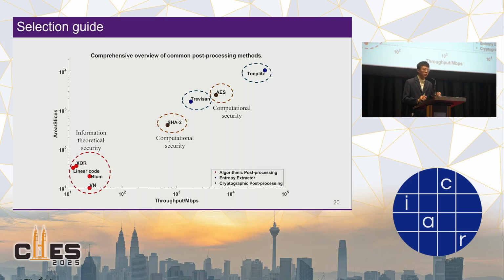You can use different single-bit extractors and different weak designs according to your specific demands. As for my configuration, the input density demand for our Toeplitz extractor is about 0.8.